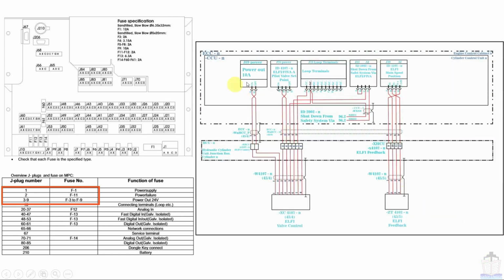So here this is the electrical diagram. So you can see J9, that is written over here, power, means this channel is used for the power, and here you can see 0 to 24 volt DC is coming out, and this is going to the LFI amplifier unit. Basically this is supplying the power to the amplifier unit.